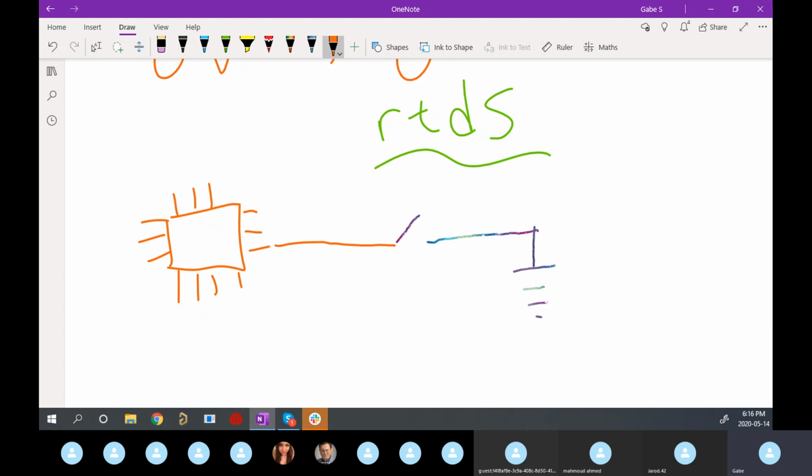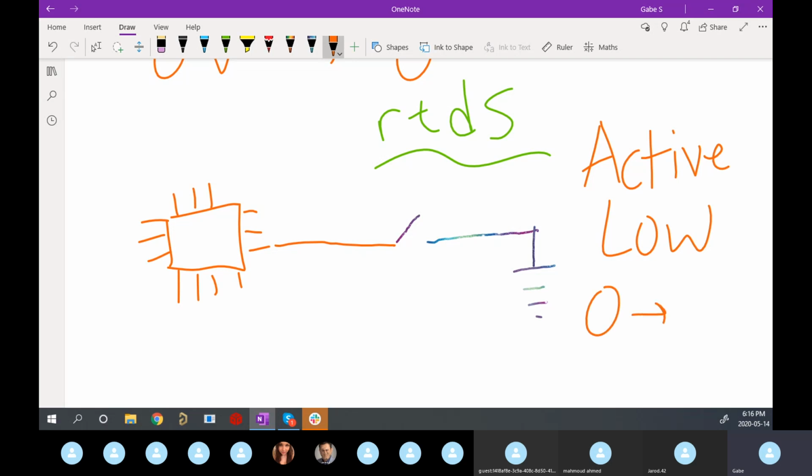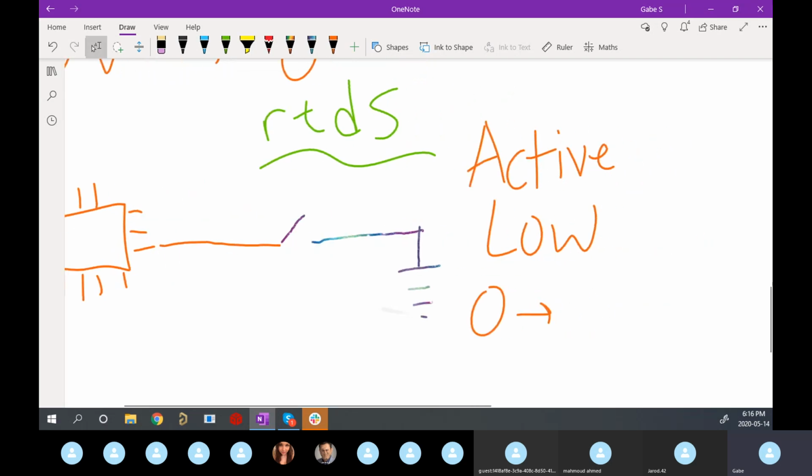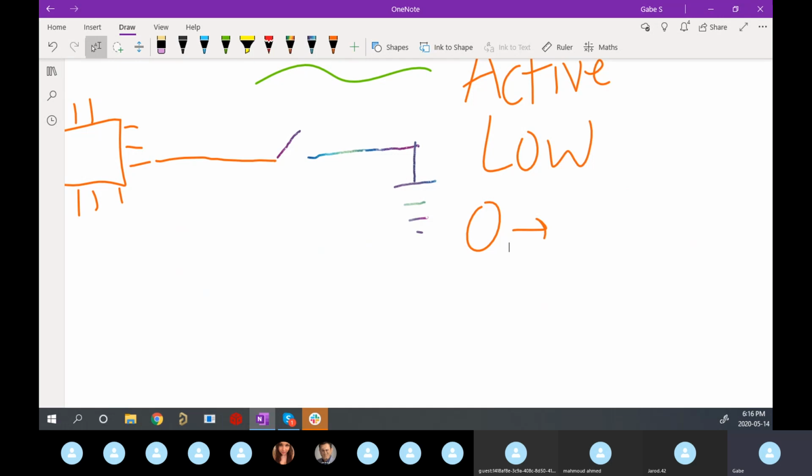But you have also this thing called active low. So active low is literally just the opposite. It's where we're saying, okay, when that signal goes to 0, that means it's activated, or it's what I expect to happen, like it's on, for example. I say the signal's active when it's low, or when it's at 0. And then when it's a 1, you can just say it's inactive.